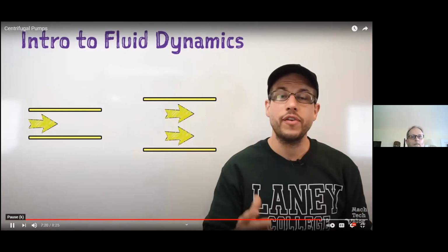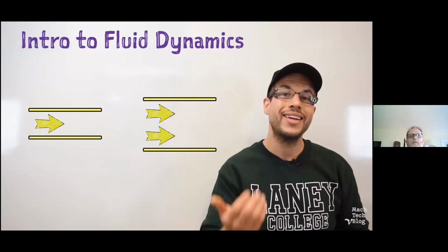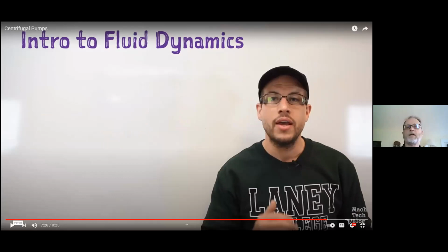If the flow rate is constant, then an increase in the size of the chamber would result in a corresponding decrease in the speed of the fluid. And that's kind of what we talked about with the Venturi meter, right? We change the cross-sectional area. So in the Venturi meter example, we shrink the area, so the velocity increases and the pressure goes down. Here's the opposite. We're increasing the cross-sectional area, which then slows down the velocity and converts that into higher pressure.